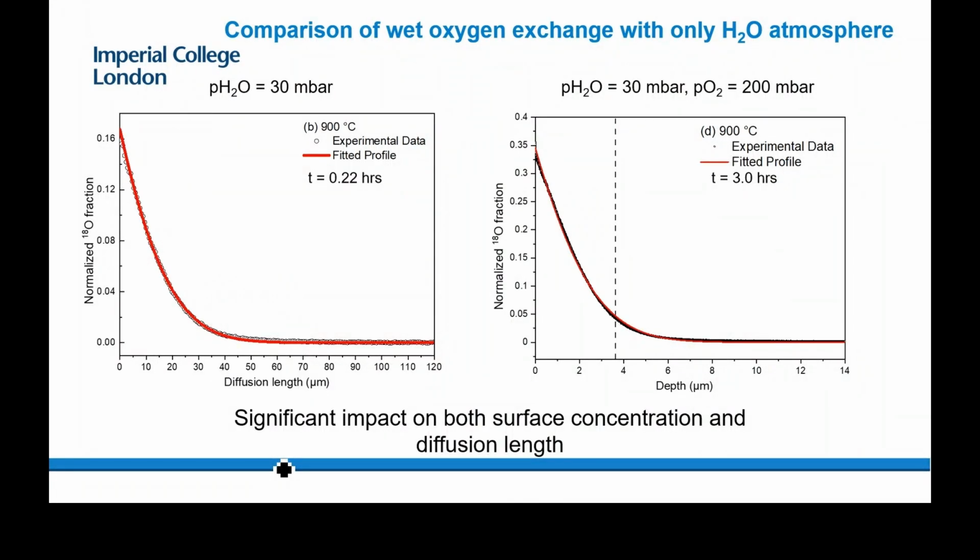Just some general questions, actually. First of all, I wasn't sure about the experimental methodology of the electrochemical impedance. Could you please describe a little bit the cell, so I can understand? Really simple. Well, yes, it is and it isn't, right? The simplest impedance measurement you can do is you have a dense electrolyte, a dense ceramic, greater than 90% dense, 95% dense. Thickness doesn't really matter. Thinner the better, because you're measuring ohmic resistance.